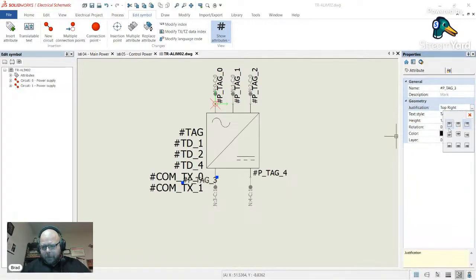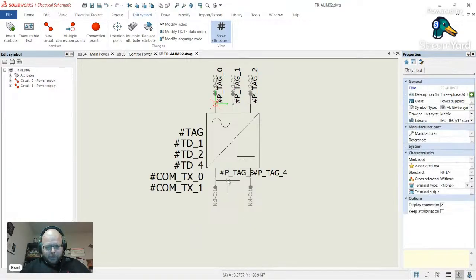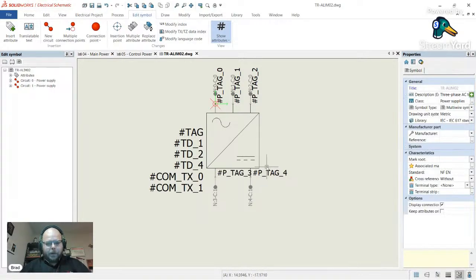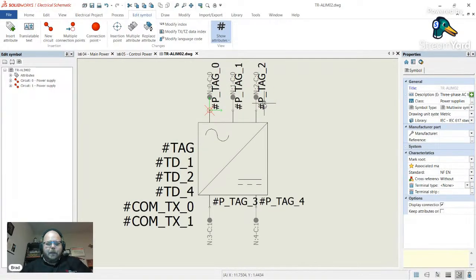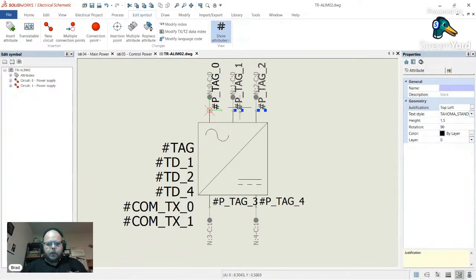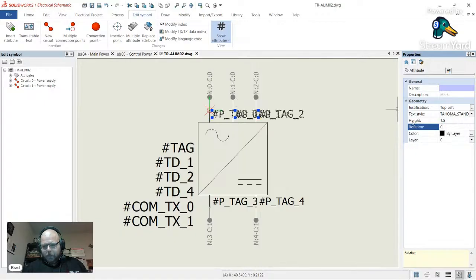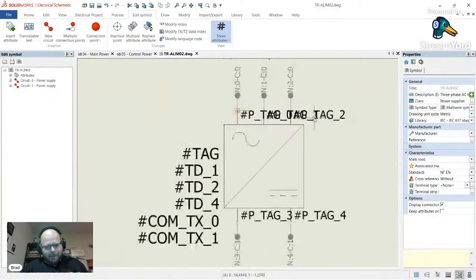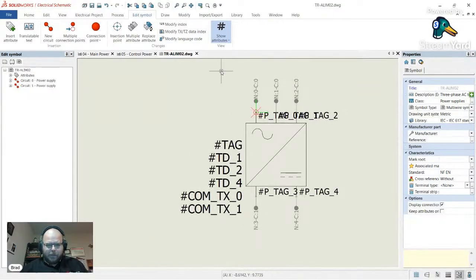We're going to go bottom right and move it and make it all pretty. Again, this is just part of being complete and being professional, right? Making these symbols look good for our, importantly, for our use. But again, be incredibly careful that you're not affecting other things that use this symbol. That's kind of crucial. Those should actually, now they overlap because they're variables, but those should actually be okay. I'm going to save that.